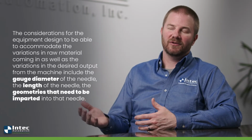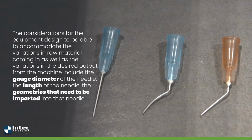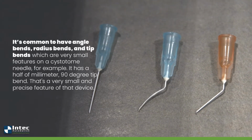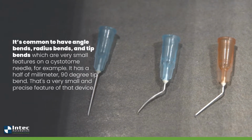So the considerations for the equipment design to be able to accommodate the variations in raw material coming in, as well as the variations in the desired output from the machine, include the gauge diameter of the needle, the length of the needle, and the geometries that need to be imparted into that needle. It's common to have angle bends, it's common to have radius bends, it's common to have tip bends, which are very small features.